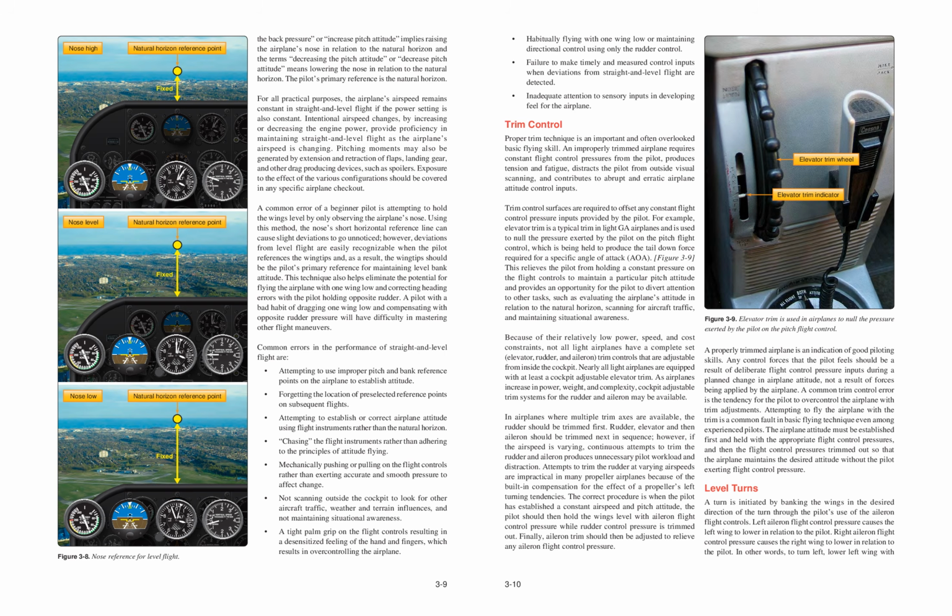Trim control. Proper trim technique is an important and often overlooked basic flying skill. An improperly trimmed airplane requires constant flight control pressures from the pilot, produces tension and fatigue, distracts the pilot from outside visual scanning, and contributes to abrupt and erratic airplane attitude control inputs.